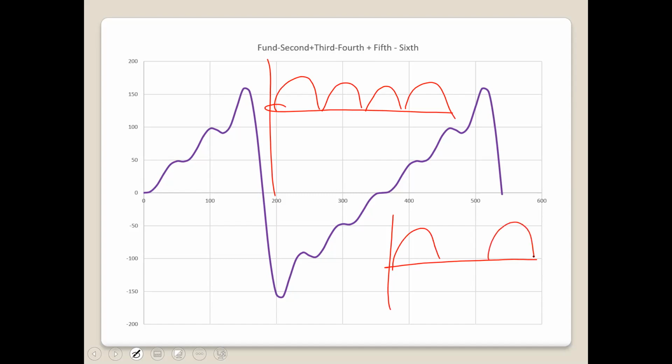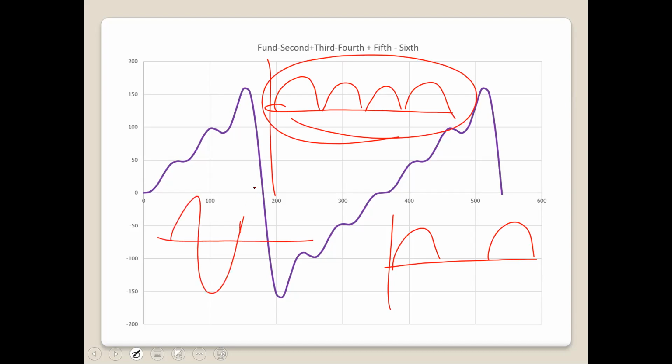That's a complex wave. So within this, what we are saying is that you're going to have some sine waves. And those sine waves, which we say will have frequencies that are multiples of the fundamental, those are harmonics. And we then determine which of those harmonics we want to filter out so that we'll get a nice smooth DC output. All right.